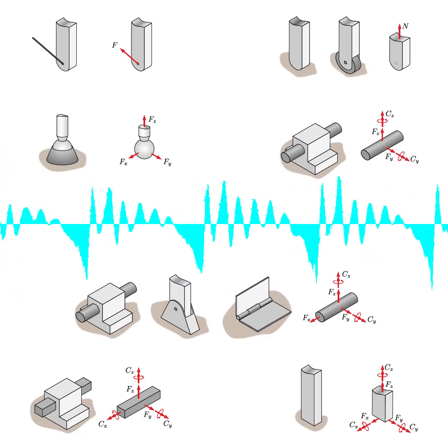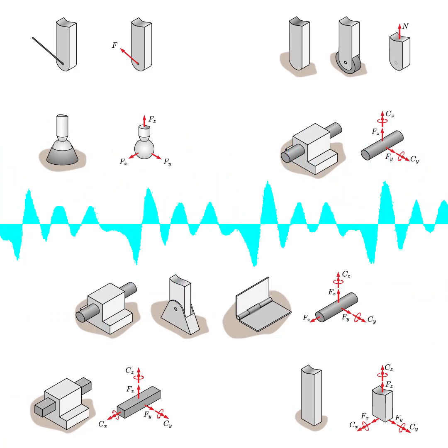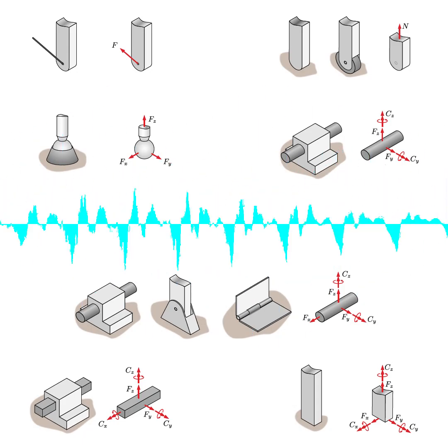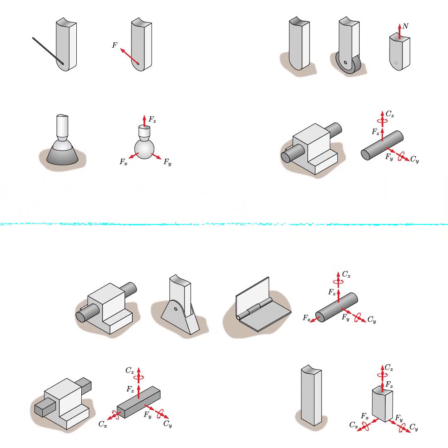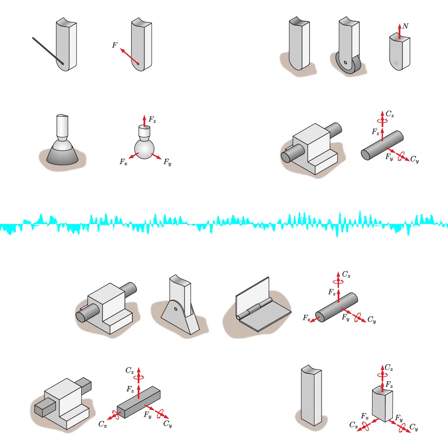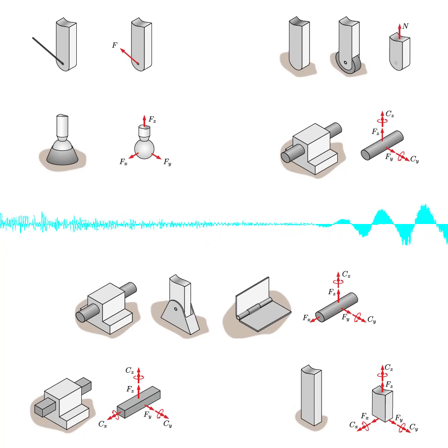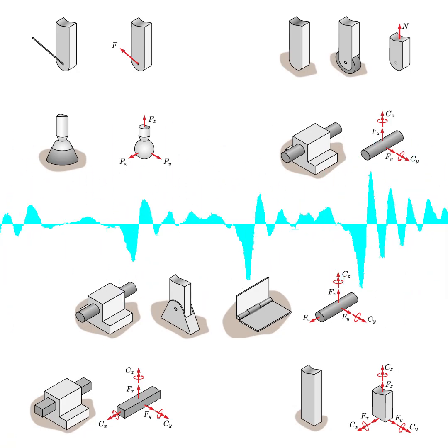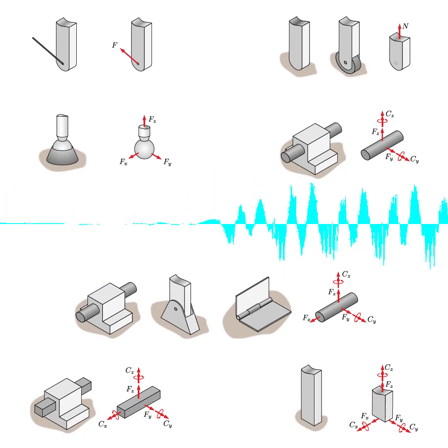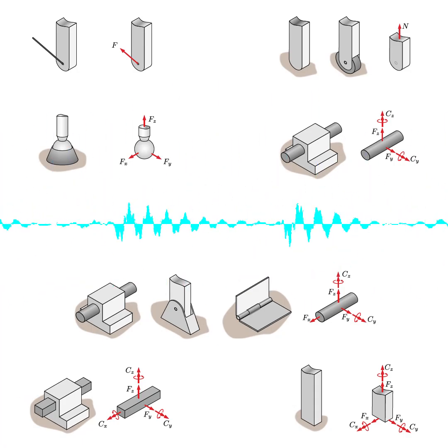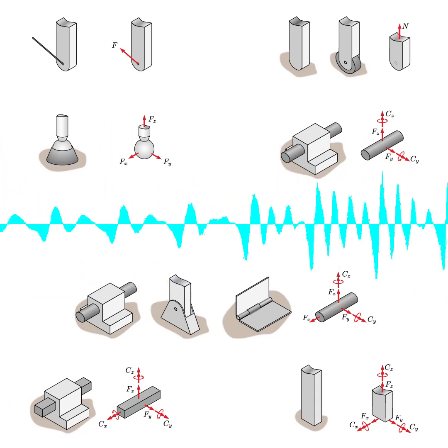Any other advice on setting up and solving these 2D equilibrium problems in the most efficient way? Yeah, aligning your coordinate system with unknown forces, if possible, can simplify things. And then the textbook also emphasizes the importance of solving any equations that have just one unknown first, because once you find that unknown value, you can plug it back into the other equations to make them simpler. Right, like a domino effect. Exactly. And example 5.4.1 in the textbook actually demonstrates this beautifully. It solves the same problem in multiple ways, showing the efficient approaches and the less efficient approaches.